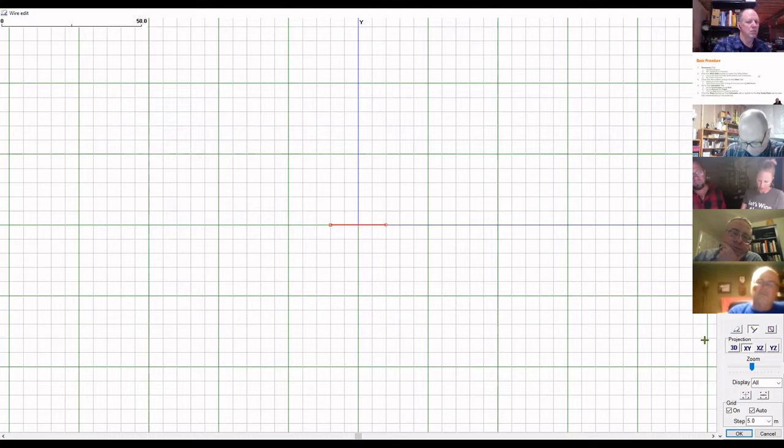We're done. That's all there is to a dipole. It's a wire, right? Now, one thing somebody might say is, but wait a minute, a dipole is actually two wires. One goes this way and one goes this way. But remember, to the software, that's just where you're putting the feed point. It doesn't care if it's two wires.